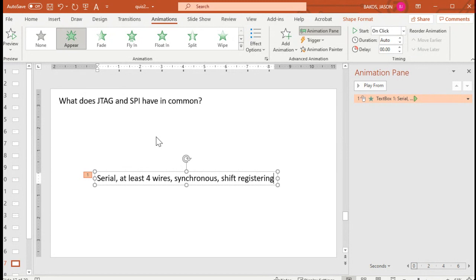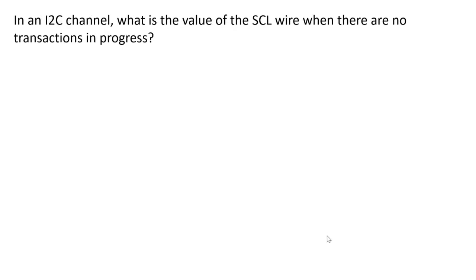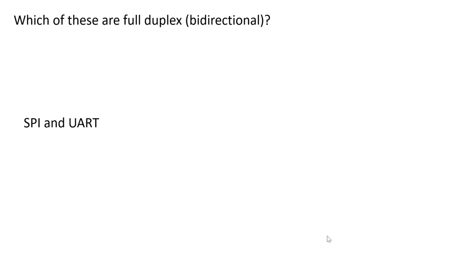So in that sense, they are full duplex. Yes. Shift register. Yeah. Full duplex. Sure. Because you got outgoing and incoming bits at the same time, so they're full duplex. Which of these are full duplex? SPI and UART, yeah.